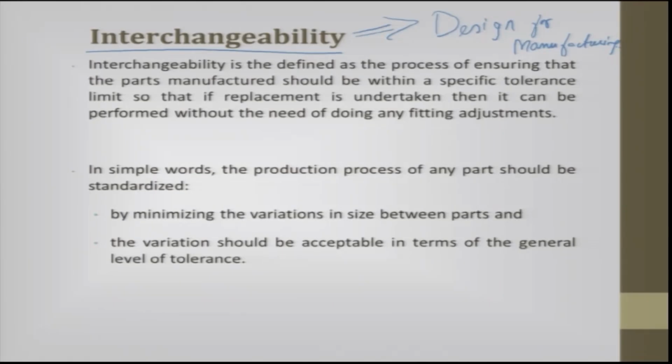As much as possible, when you develop a product, try to use standard parts. One, for those standard parts you will always have vendors who will be competing and giving you a price which is economical. Two, you do not have to depend upon one source, you can have multiple sources. So, the advantage is that you can make your product more economical and you can make your product very quickly.